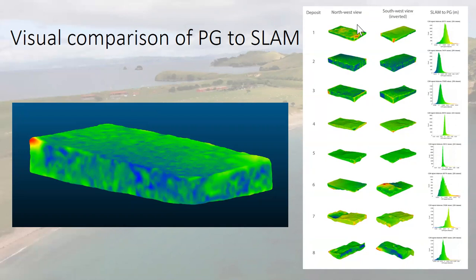With the SLAM data, considering it was more difficult to establish a surface on the edges, that's not particularly surprising. Most modeling software, especially photogrammetry and SLAM, have trouble with corners, particularly with the type of data that we're looking at, because we're thinking about a trench. It's not a hard corner like a perfect cube. It's a little bit rounded and has trowel marks and rocks and things. So that's where we're getting most of the discrepancy.